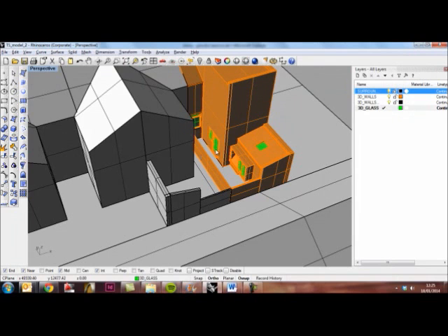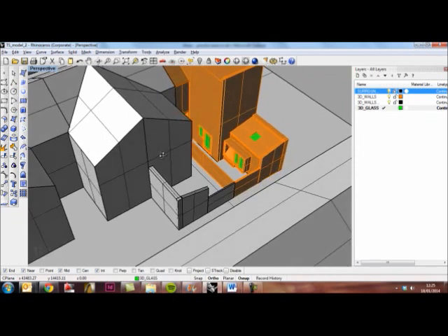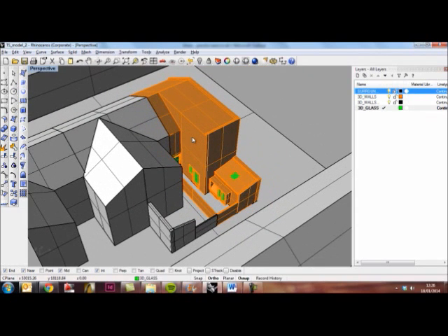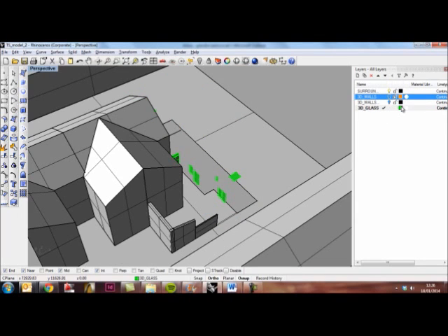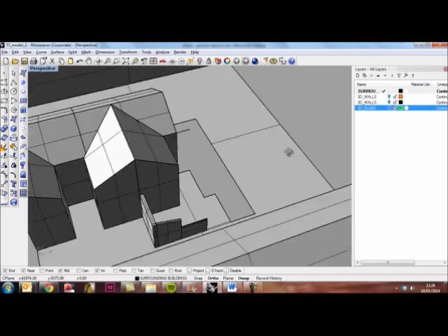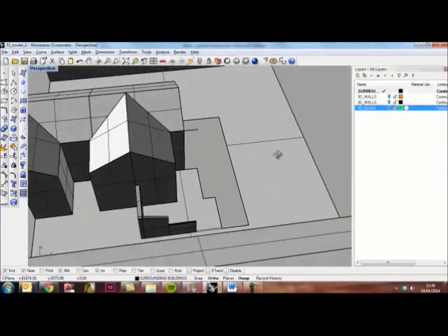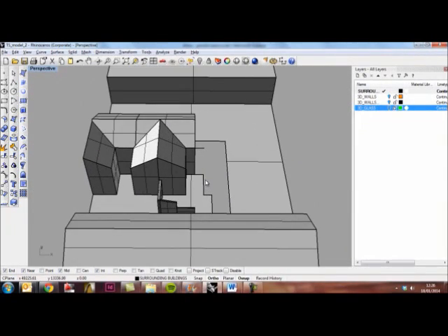So what's important? You need to model your homes to a level of accuracy that is relevant. That means if I show you how I've built this model, we start at the very outside. I've built this in Rhino. You can do this in lots of other modeling tools, but I'm assuming most of you are based in Rhino, in which case this is going to be the most relevant one.